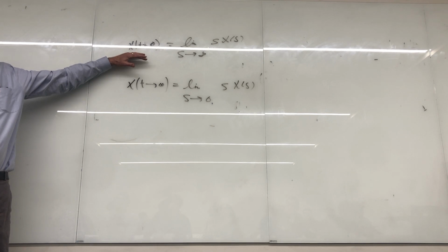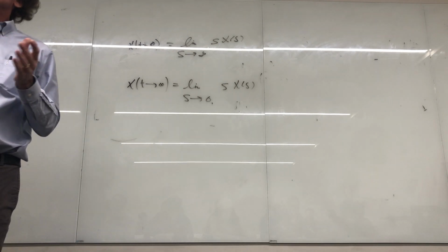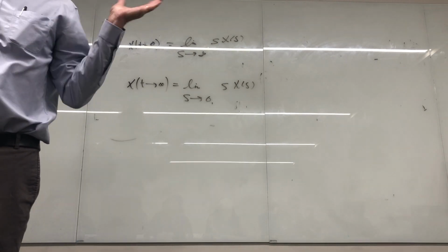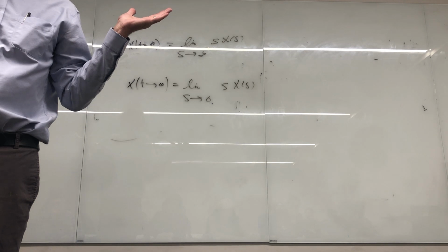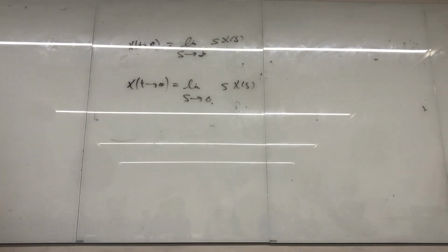Anything that's stable is not going to go to infinity when time goes to infinity. Anything going to infinity, a voltage, a current, anything measurable like that, means the thing blows up. That's what it means. It's not stable. If it goes to a constant, it's okay, even though it's not preferred. If it damps to 0, that's the one you want. That's very stable. It's an unconditionally stable solution.